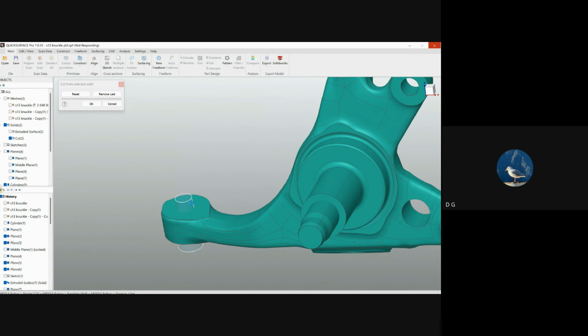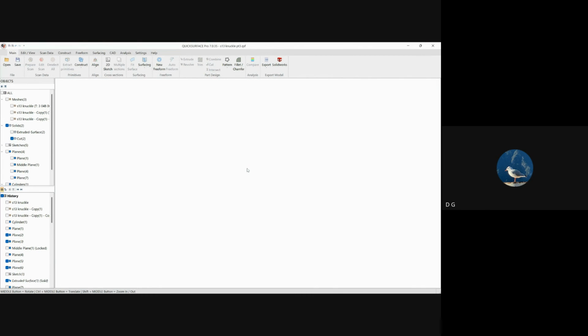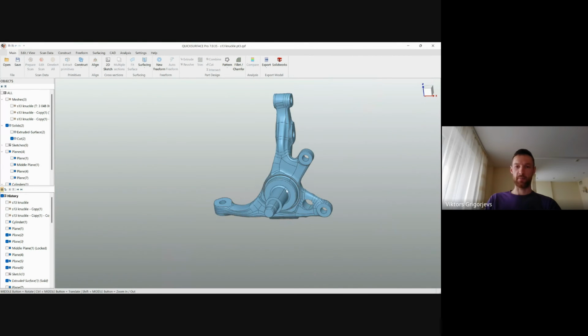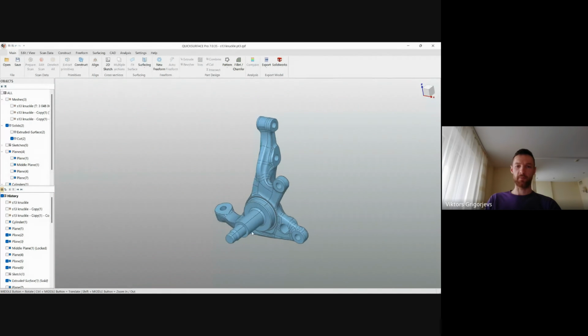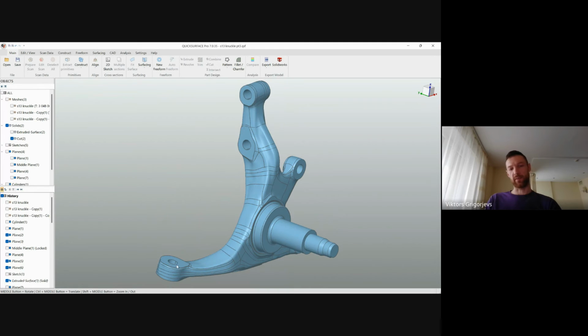I have a question. Yes, of course. What's the better way, to cut from selected solid or use the trim command? Basically, it doesn't matter. It depends more on how you see your workflow. But in this case, for example, if I have completely these features, I can trim this feature. I can cut that feature away from the solid body with one click.